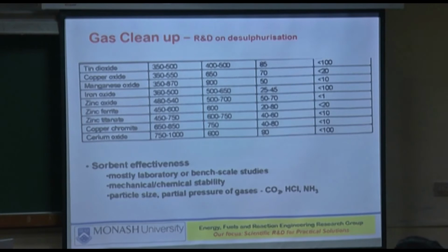The problem is, one other problem, these are desulfurizing beds, and these are mildly fluidized, mostly fixed beds. If you have fine particles in the bed, keeping the fine particles fluidized is not that easy.